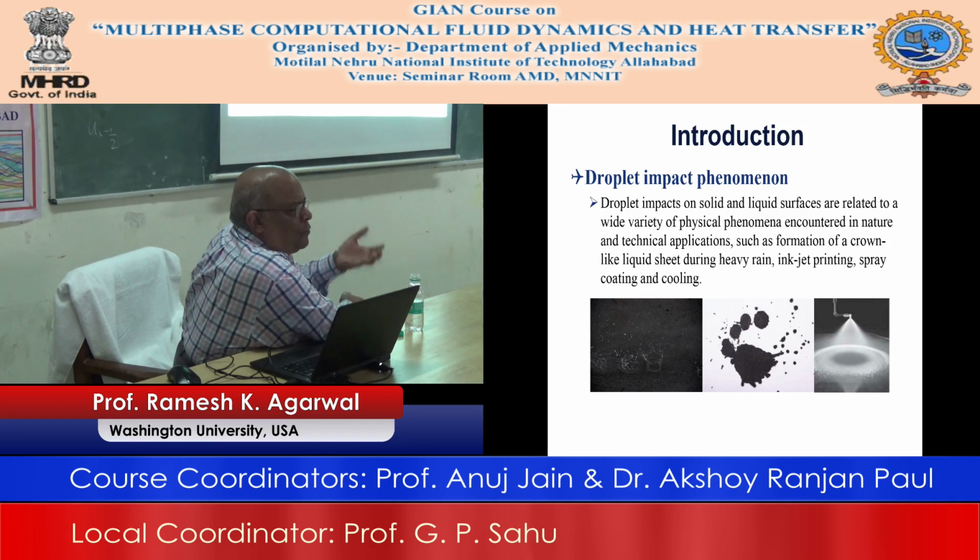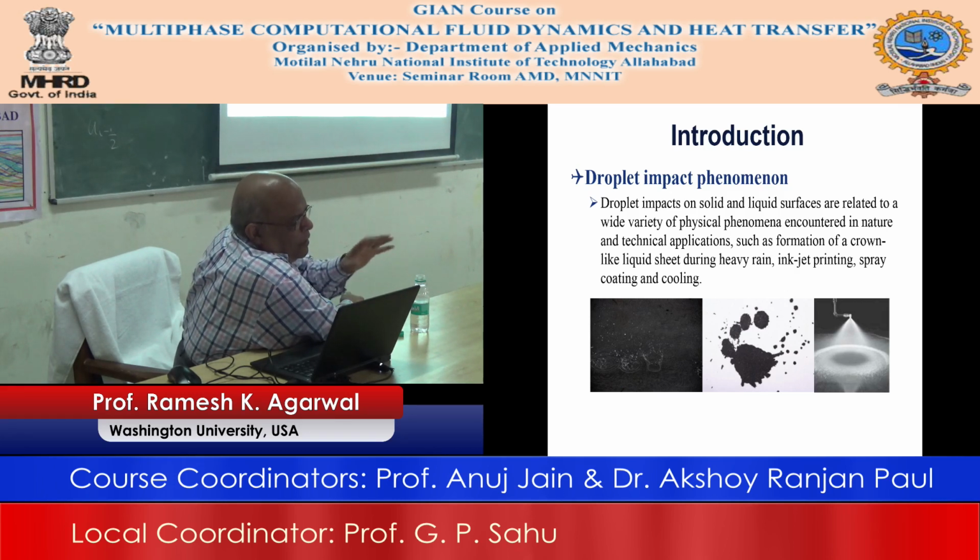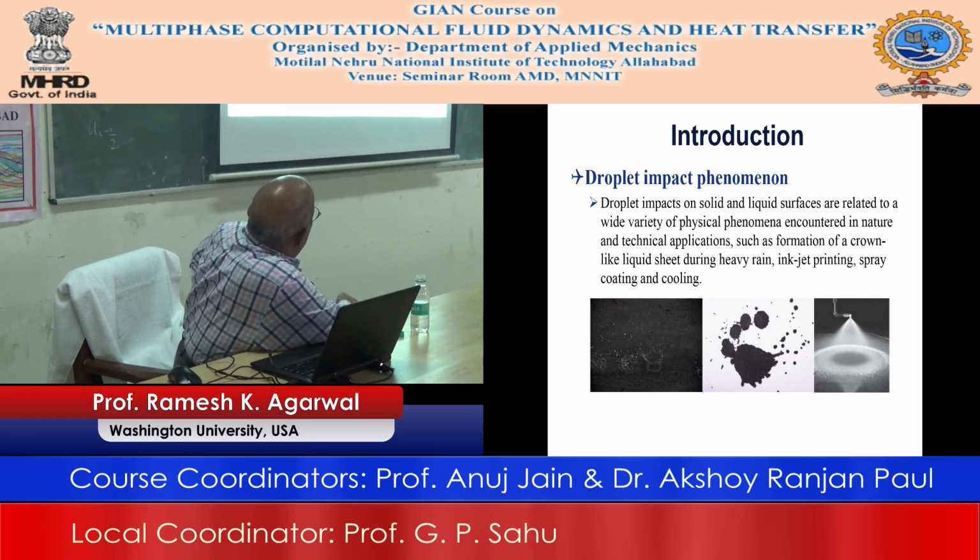So then you have to use a two fluid model or some other model to capture the gross effect. Okay, so I will keep on repeating myself that please don't think that this model problem that I am showing you to capture the effect of the surface tension via the Weber number can be done if you have millions of these, you cannot do this for each droplet, okay. So then you use the two fluid Euler model. Okay, and that can capture in gross the effect. Okay, so that is what is done.